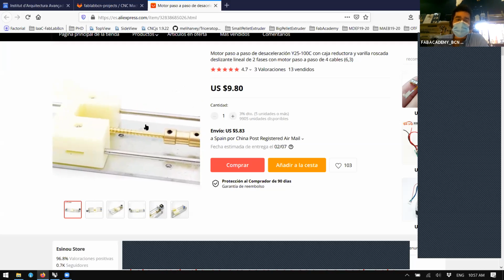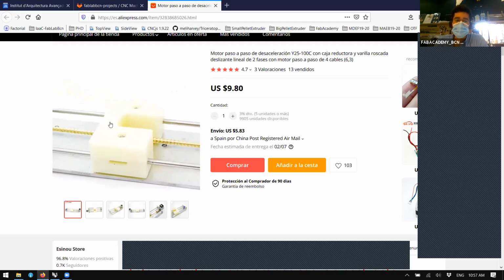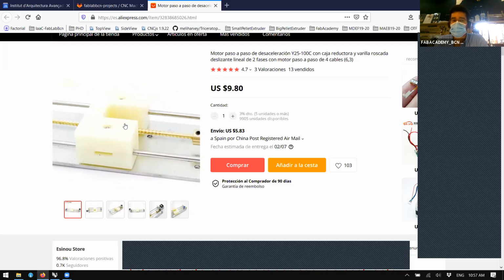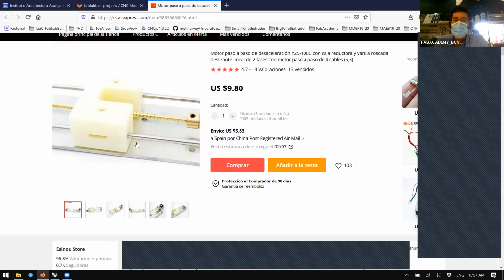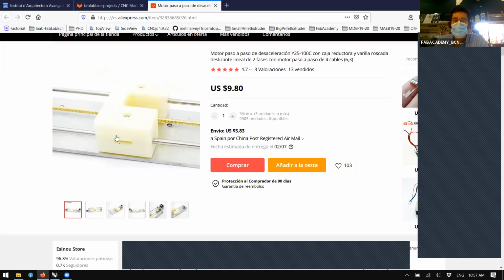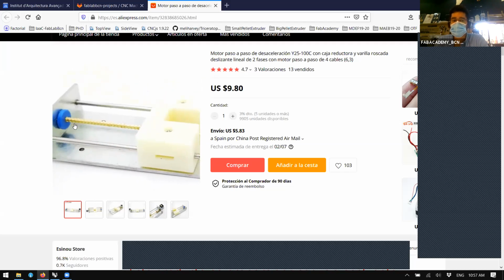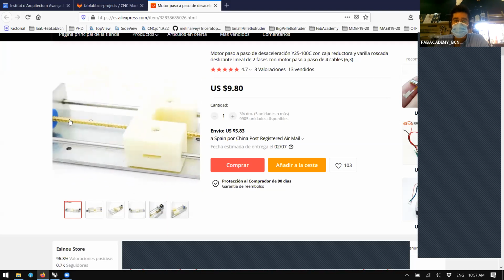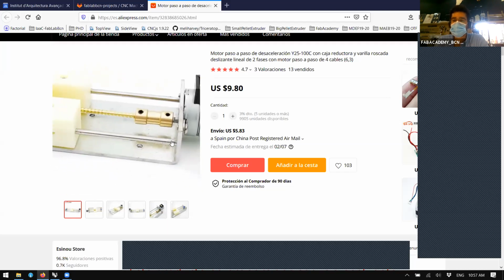This goes to a coupler, to a lead screw, and to a nylon sliding block. We think it is nylon. They don't specify, but from the color, we think it's HDPE or nylon. The block goes into two small 3 millimeter steel bars that make the sliding part. So the total length of the white part, left to right, is 100 millimeters.